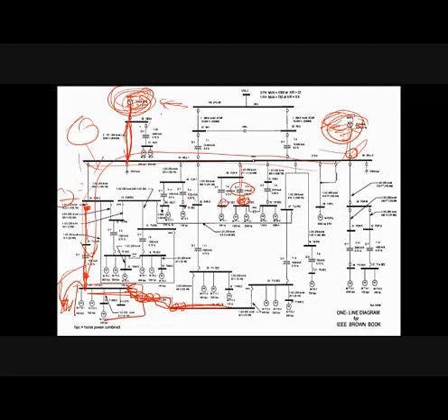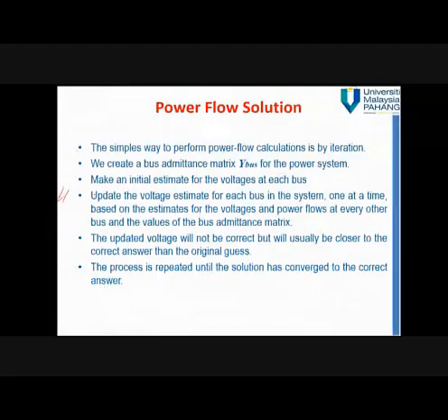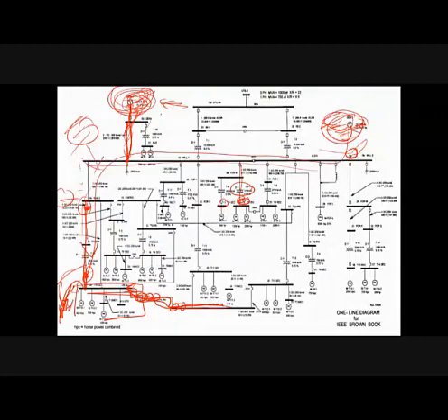What happens if many generators are disconnected consecutively? Let's say after this generator is disconnected, and so on. As long as this fault cannot be cleared by this circuit breaker on the transmission line, this generator is overloaded. When this generator is overloaded, it will cause all the other generators to also be overloaded. And because of that, all generators are disconnected from the network and cause the major blackout in Malaysia last time. That's a contingency study.